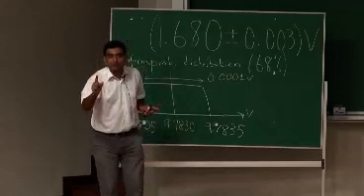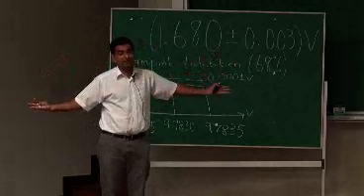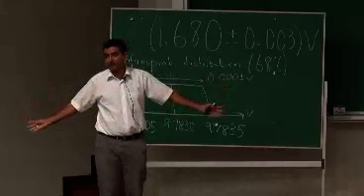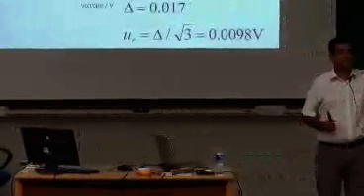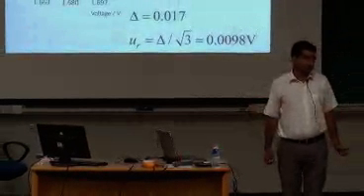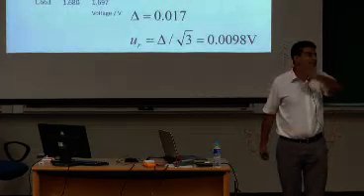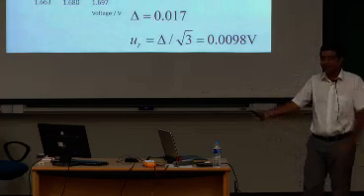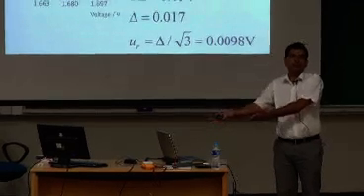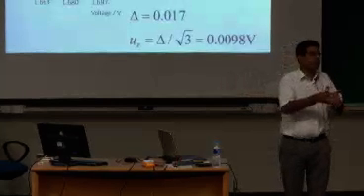So remember, in this approach, even if you take a single reading, a single measurement, there is a probability distribution function associated with it, even though you are not taking multiple readings. But there are other sources of uncertainty. And remember, this is a type B uncertainty because I am just doing the experiment once. What other sources of uncertainty could there be? And remember, I am never using the word error, only uncertainty. What other sources could creep in to give you an uncertain result in this simple measurement of an EMF with a simple digital voltmeter?